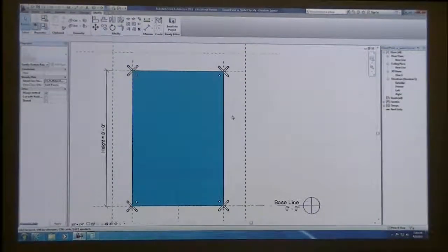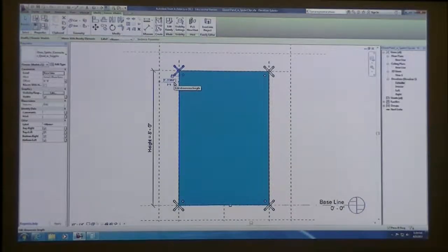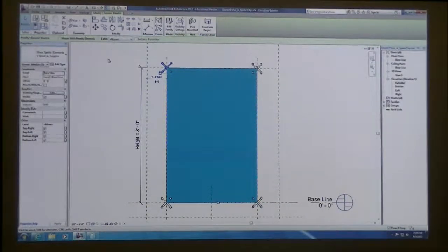Do those parameters come into the model? No. So what happens is, since the spider clip was a family, this family is getting embedded within this family. Those instance parameters only travel one family at a time. So we can only toggle those on and off in this family. And what you would end up really doing is, because once this gets into the project environment, you can really only select panel types, because remember when you clicked around in the grid system, you would toggle and select from the pull down menu the ability to select a type of panel to be placed.